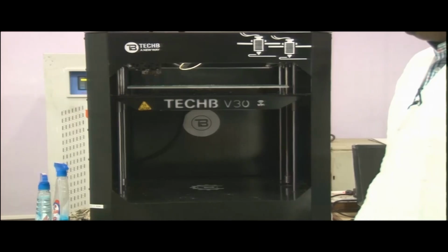FDM machines produce products with precision, but the precision level in SLA is higher. Higher resolution objects are more possible to produce in SLA because resin is there. The resolution is primarily determined by the optical spot size either of the laser or the projector, and that is really small in SLA. In FDM it is the printer resolution, which is a factor of the nozzle size and the precision of the extruder movements. That extruder we will discuss in this demonstration as well.